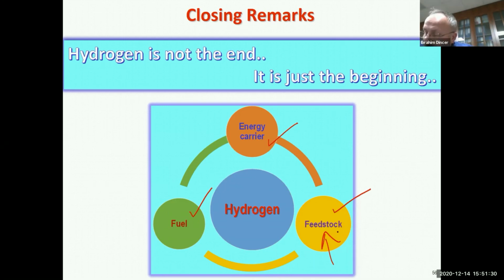And then coming down to the microwave-based hydrogen production. Exactly, yes, the efficiencies will be low, because a high energy density is needed, because you are talking about microwave, and then trying to separate. And of course, what is most efficient is electrolysis. And even in thermochemical cycles, depending on the cycle you choose, the efficiency is going to be from 20 to 40%, depending on the integration you do and the heat recovery you manage. But overall, the efficiency here is very low.